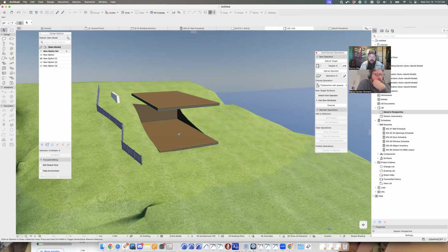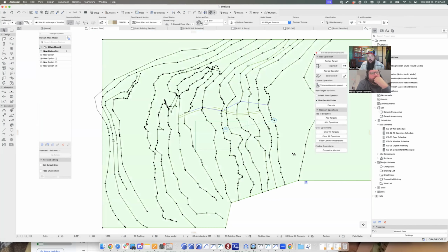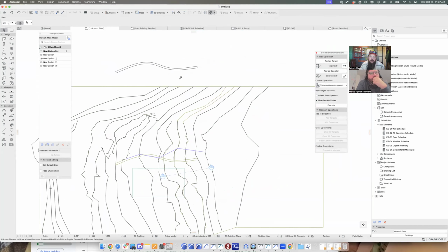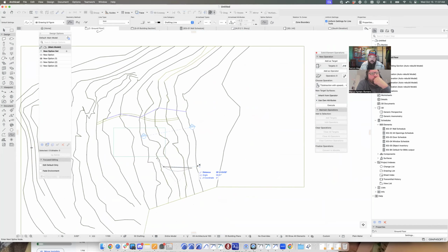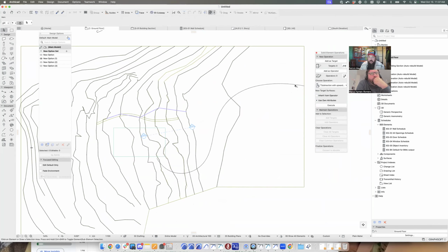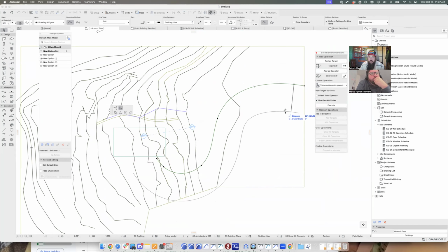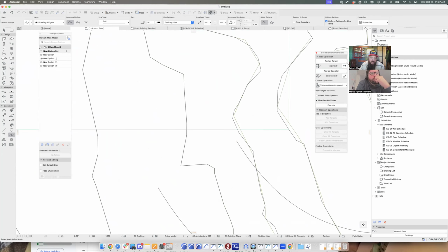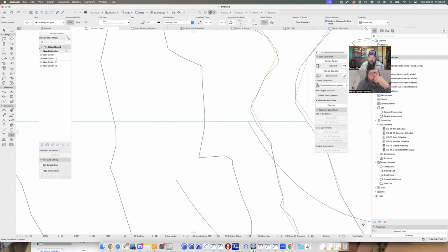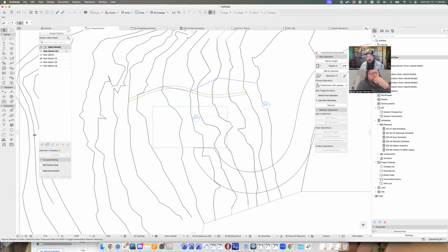Now there are some cool things you can do with this. Let's say I have a driveway, as another for instance. If I have a driveway that comes around something like this across my site, and I'm going to say that this driveway is sort of 12 feet wide, I don't necessarily want a separate mesh that I'm trying to match into my main site mesh, because there are always going to be cases where it doesn't quite line up or doesn't feather out. Maybe I do need it to be a separate mesh in order to show retainage or build up or exact slope.